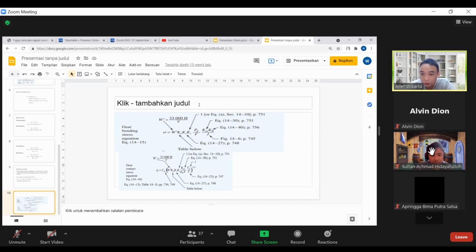So we have to consider them when we calculate the sigma, the stress that happens in the spur gear. And we already included it when you determine the W1T. Is it correct or not? Not you, but your friend last time, when he calculated the W1T, he already included the KO, of course. Yes, right?